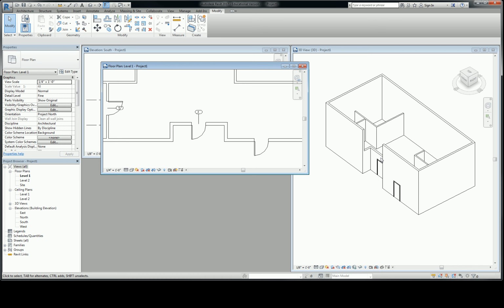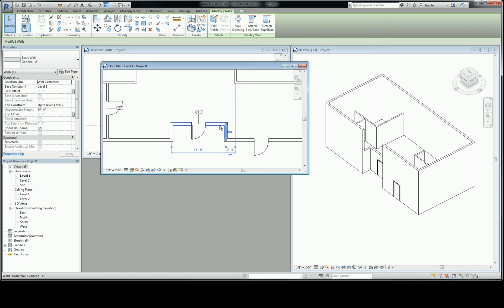It probably would work for the height here too, but the last thing I want to show you guys is how do I get this thing to actually be the height of these exterior walls? Same thing, you're just going to select all 3 of them. Then if you look over in the properties of that wall, going down, there's a location line, base constraint. Actually, let me split this off into a separate video because I want to show you a few things with it.